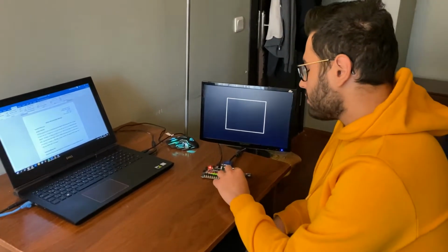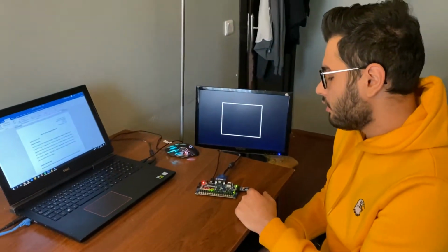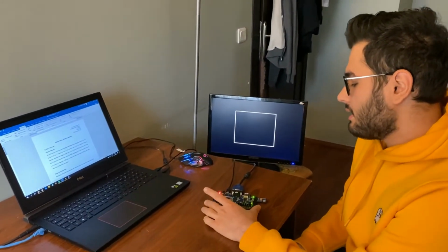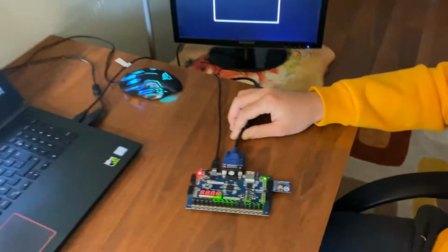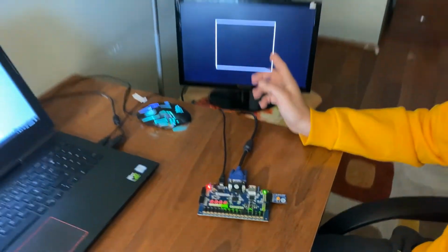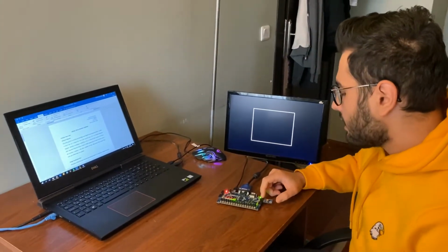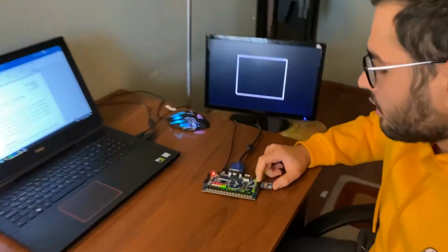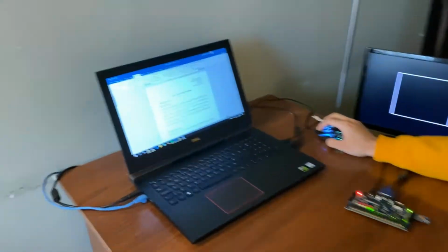So my voice-to-text converter uses Digilent PMOD MIC3 for voice inputs, and I am using a Basys 3 board for my VHDL programming. And I want to demonstrate my outputs on the monitor by using VGA code. The microphone works based on an SPI interface, SPI interface code.